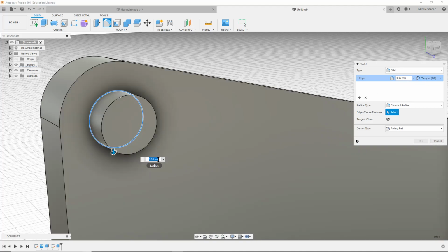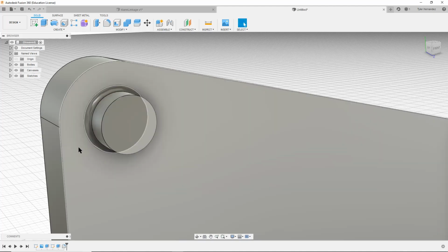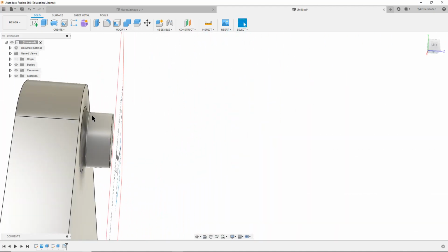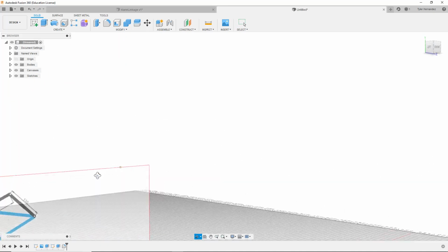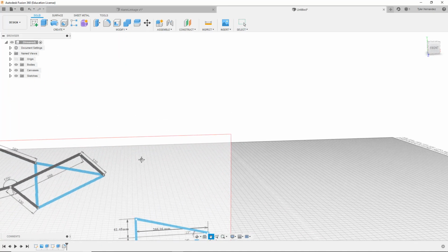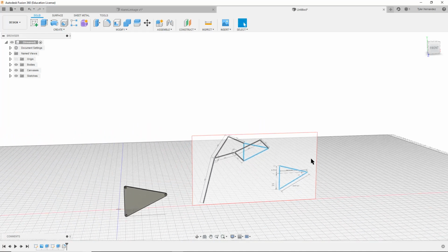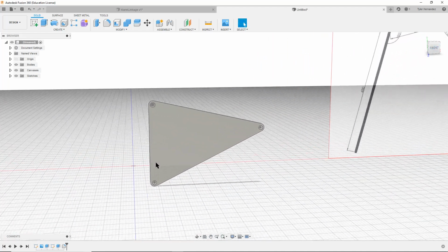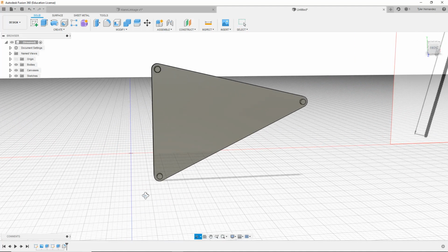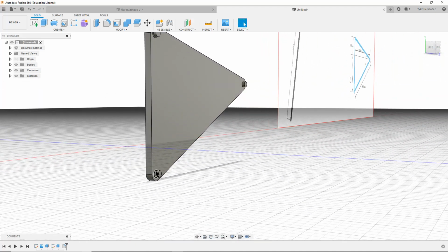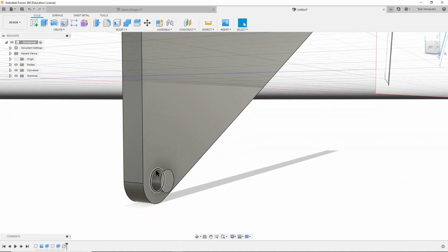and I select a fillet radius, in this case I'll do 0.1 millimeters, it's going to give that sharp edge a 0.1 millimeter curve to it. So it's not as sharp, it's not going to be a stress riser anymore. What just happened? There we go. So that's a nice thing to do typically when you're making a product. So I'm going to go ahead and do that.